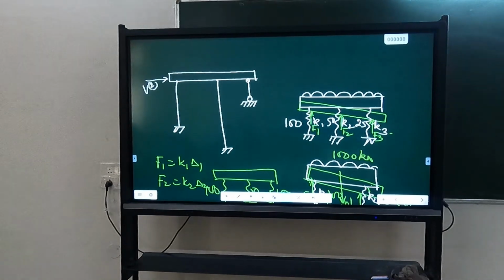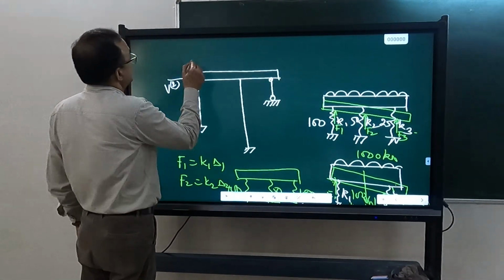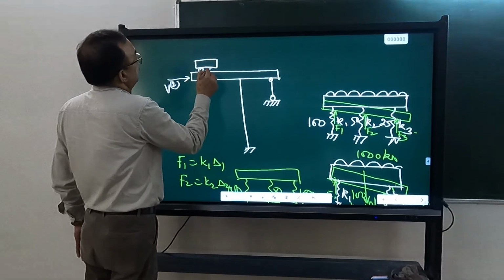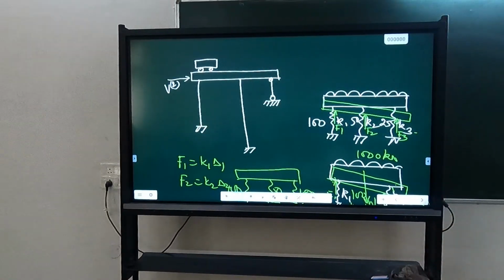Yes. So any problem here if the hinge forms on the superstructure? Serviceability. Okay. What do you mean by serviceability? What problem? There may be more deflections if plastic hinge will form there. So first of all, superstructure is to be always designed for vehicular load. Vehicular load is not heavier than the superstructure itself, but it is much heavier than the load which we are having on buildings.